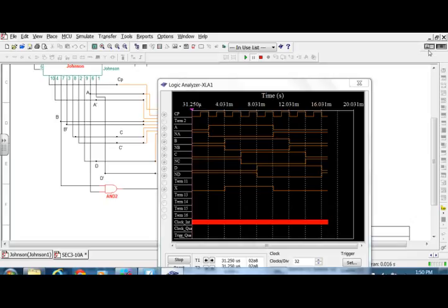Okay. So now the issue is, A, is what we're seeing correct? All right. So I got this internal clock down here, which is a clock pulse going on that's sampling these other things. That's what the red guy's doing. So there's my clock pulse going on and off. And the Johnson counter, it looks like on the negative trigger, it's changing.